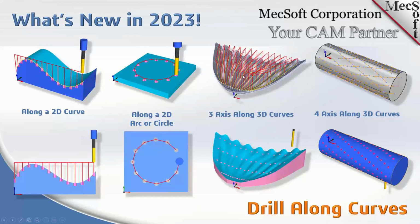If you look closer, I'm going to show you this in a demo, but if you look closer up here, each of those drill points, the start of the drill cut will lie on the curve, and then it'll drill the depth based on that point along the curve. And you can see how that looks in the simulation down below.